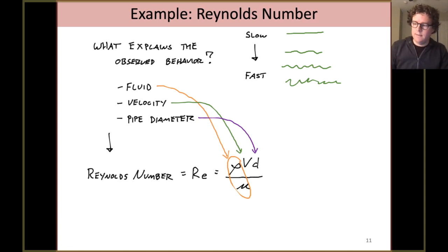And later in this class, we'll look at Reynolds number as we predict things like energy losses associated with turbulent flow. So this is an example of the sort of dimensionless grouping that might shake out as being really important. In building a scale model of the Marmot Dam, we might have checked to make sure the Reynolds number in our scale model was the same as the Reynolds number that we saw out in the field, in the full-scale dam.